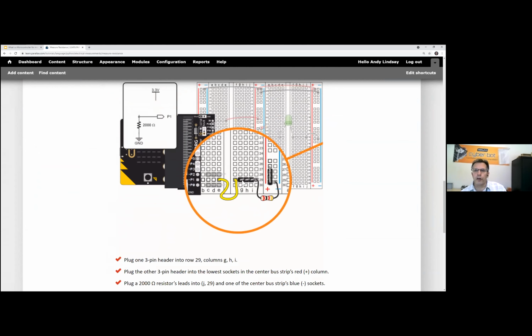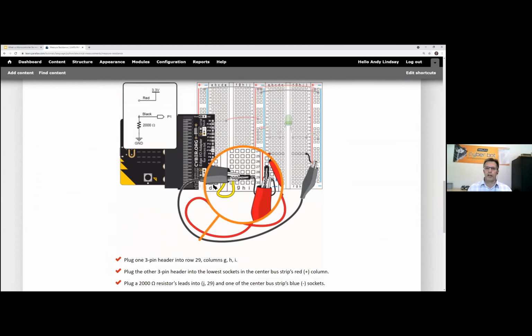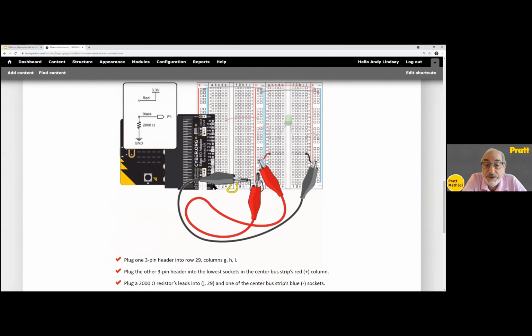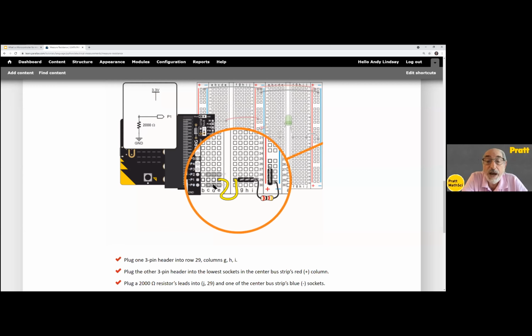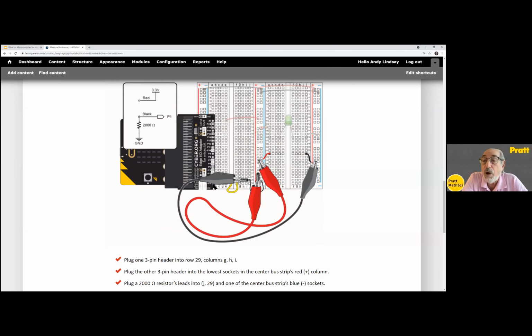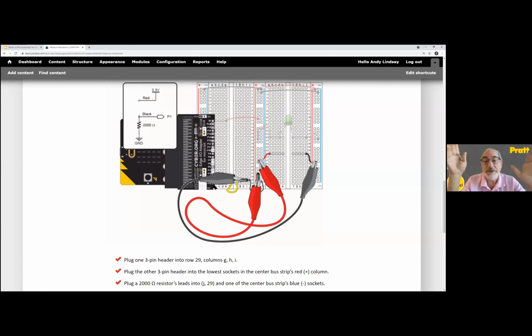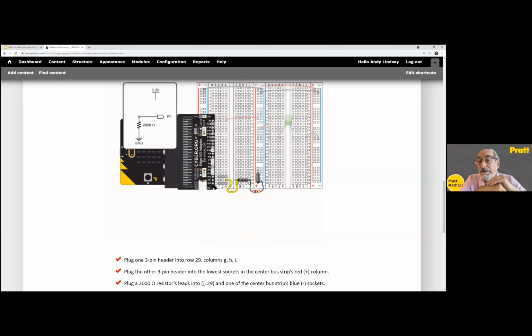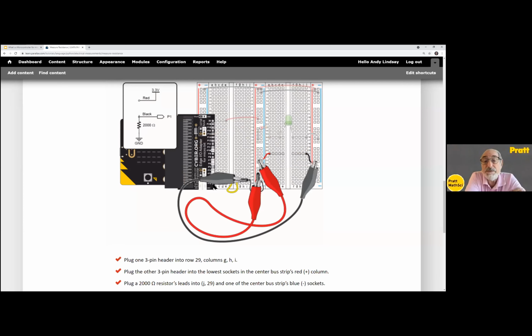And so one clip goes there, got it, and then the other clip would go underneath. And in fact, I think it's a very bad idea to have the circuit with the 3 pins so close together. And I would suggest you've got all these little jumper wires, just jumper it up to the top so that there's plenty of space and there won't be any shorting out. Students that are unfamiliar with the use of these clips, they're going to short those two together all the time.